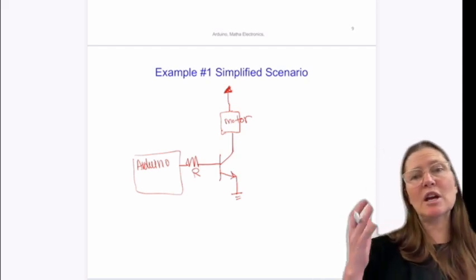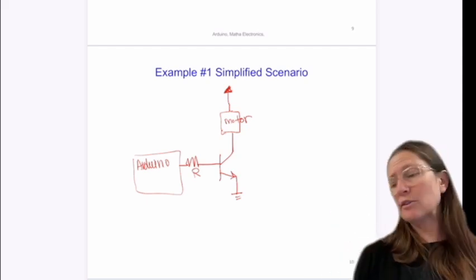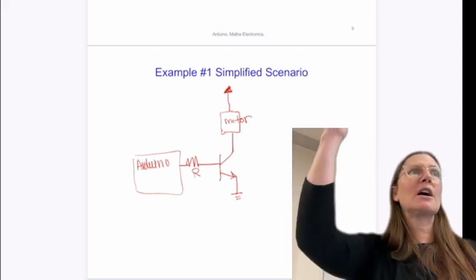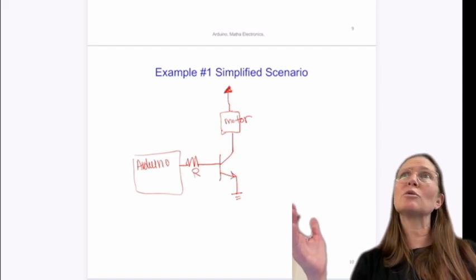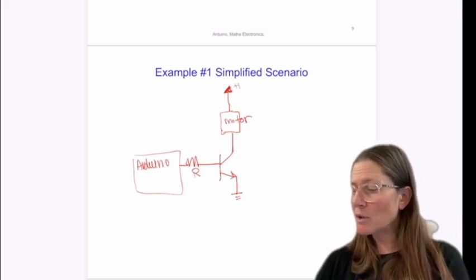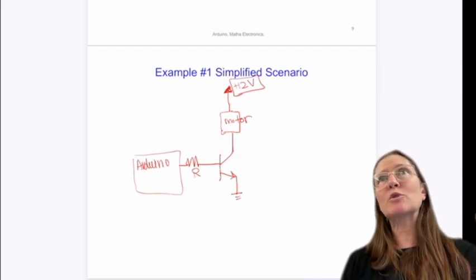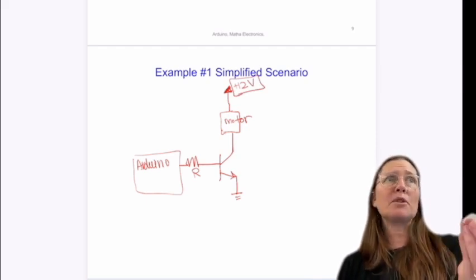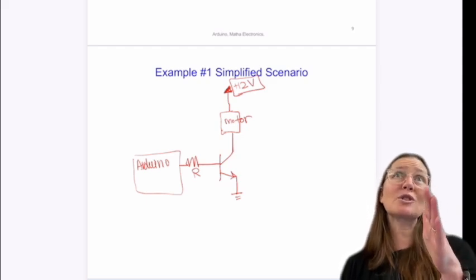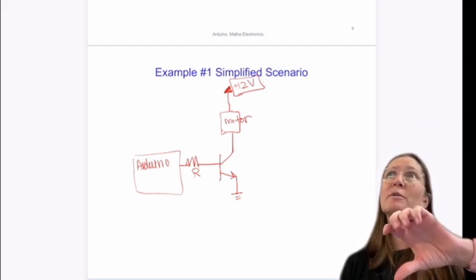Most of the time, you either want it to be on or off. You can then use the resistor that's connected at the base to control how much it's on and how much current will immediately go to the motor. With this being hooked up to 12 volts, that can supply as much voltage as you need for the motor. And then once it turns on, it creates almost a short circuit, and so you get as much current as you want drawn from there too.